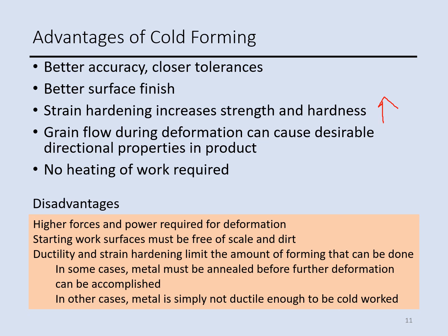In cold forming, the structure of the grain will be changed. For example, you remember we have grains in metals or alloys, and these grains have one original shape. When we deform it through cold working, they will be stretched in one direction, like this.